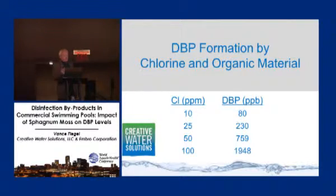It seems intuitively obvious, but if you take biofilm or contaminated sand from a sand filter and treat it with chlorine, you get the production of disinfection byproducts. The reason we have to use such high levels of chlorine is because in this static batch system, the chlorine gets sucked out so quickly that if you put 100 parts per million in there, you'll only recover less than 5 parts per million after 5 minutes.